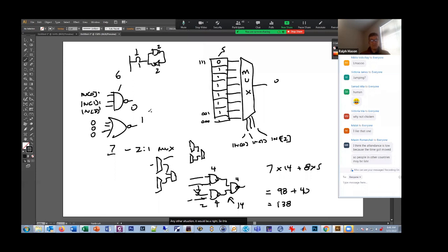So instead of putting the memory in here like we just did, let's erase all this memory, and instead we're going to write into this memory. When it's 0, 0, 0, we're going to put a 1 here, and everywhere else we put a 0. And guess what? We just rewrote this memory, and now we've got a NOR gate. That's pretty cool. Using this little lookup table, it turns out we can build anything of 3 inputs.